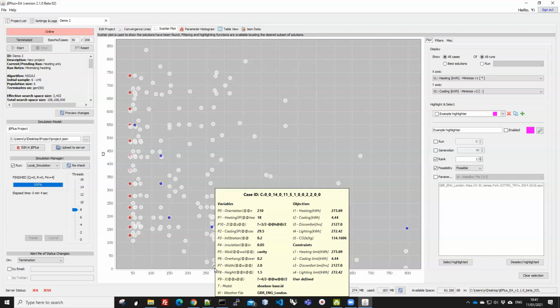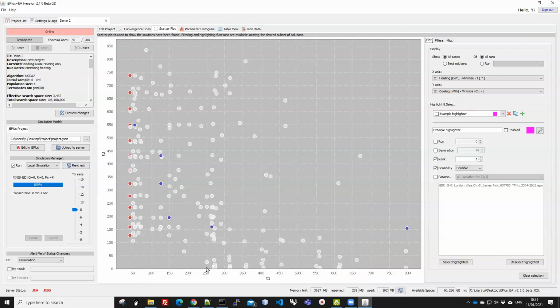Is it comfort? Not quite yet. I'll go there later. Well, you actually need to somehow combine the cooling consumption and the heating consumption. Say, for example, if both heating and cooling are provided by electricity, then can you calculate the annual electricity for cooling and heating and use that as an objective instead of cooling and heating separately? If you can, then you're effectively combining these two.